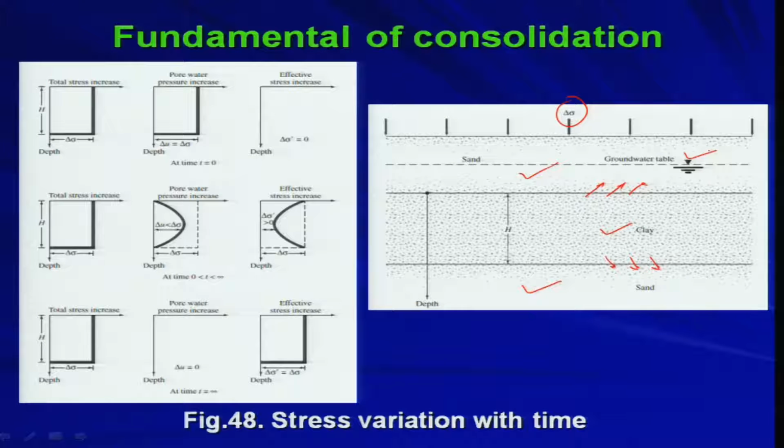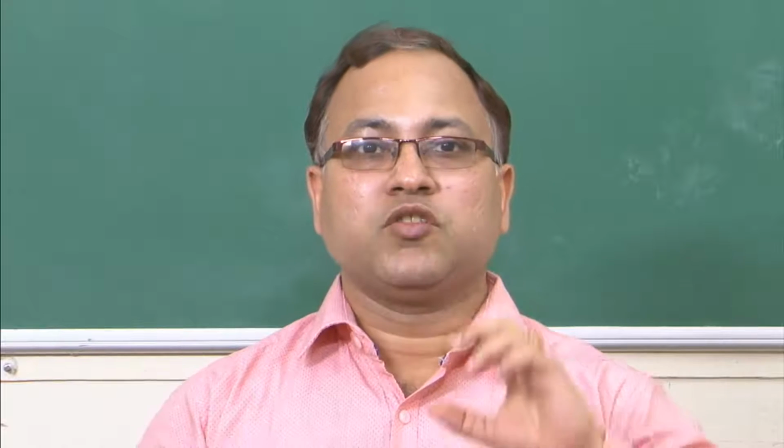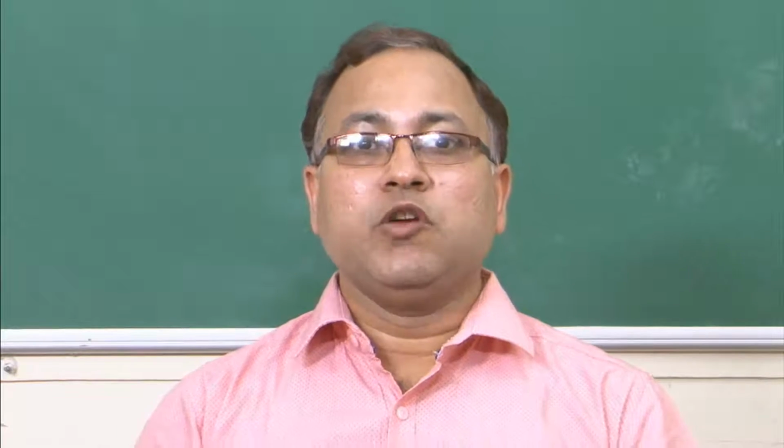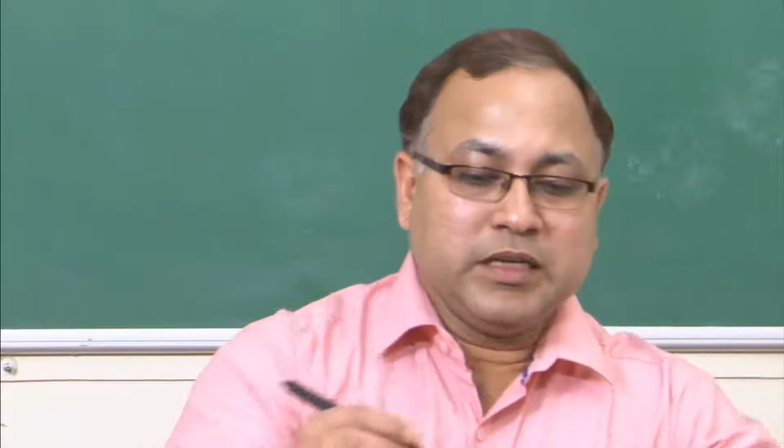Now, what will happen? Once you apply the load, immediately at T equal to 0, the total stress increase will remain the same, because you are not going to change the stress increase during the process. So delta sigma will remain the same. Therefore, your total stress increase will always be delta sigma, whereas there will be a balance between the pore water pressure buildup and the effective stress enhancement. So this is at T equal to 0.